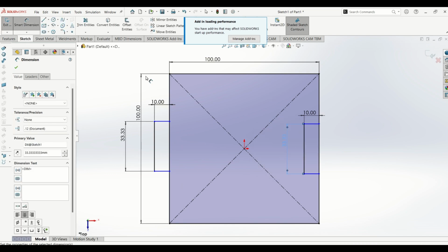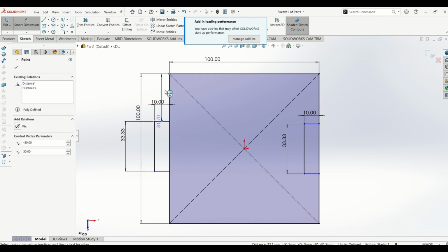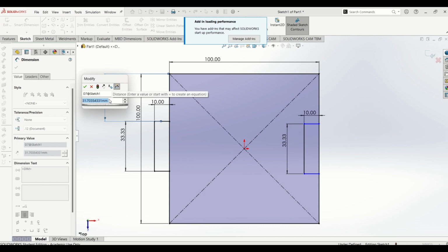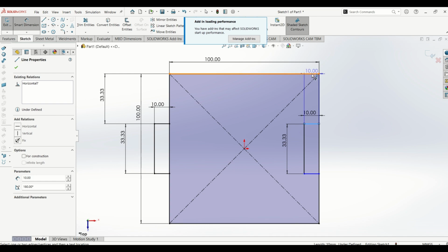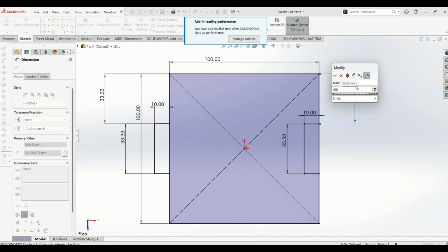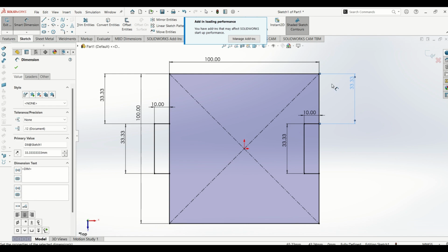And then we need to position on the cube our two little tabs. So we're just going to click between the two lines, one here and one here, and we're going to do the same again, so 100 divided by 3. We're going to do the same here and here. To measure between two different points, you need to click on 2 points. If I just clicked this line, it will give me that entire line, whereas because I clicked this point and this point, it gives us the dimension between the 2 points.